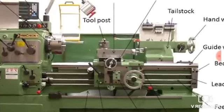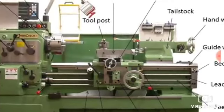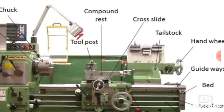After that there is a tool post for keeping your cutting tools. Here you can use a single point cutting tool, mostly on CNC lathe machine. On lathe machine single point cutting tool is used. So here you can keep either 4 or more than that single point cutting tool over the tool post. Then there is a compound rest.